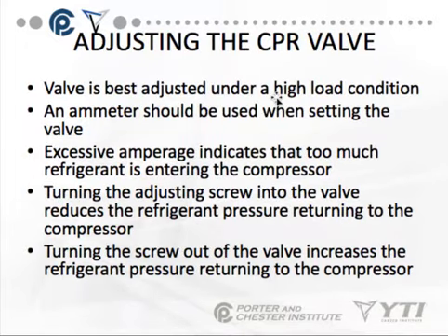Okay, to adjust this valve, we adjust it under a high load condition. In other words, not normal operating conditions. In other words, we want our case higher than normal. We want to put an ammeter onto the compressor circuit when we're setting the valves. We do not want to have excessive amperage.